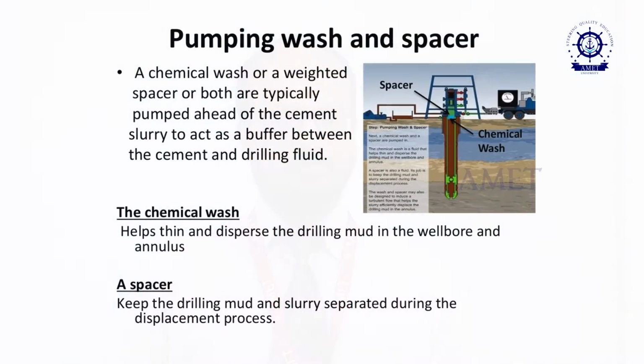So further you have to pump spacer. Once the chemical wash is sent, further I have to send spacer. This spacer creates the gap or separation between the cementing as well as the drilling fluid.